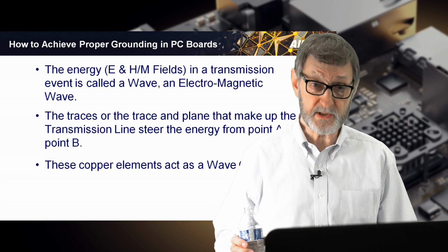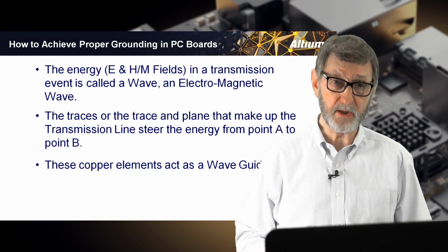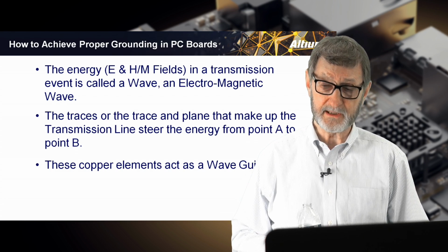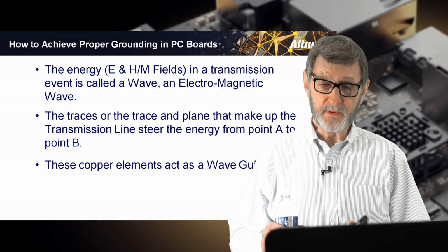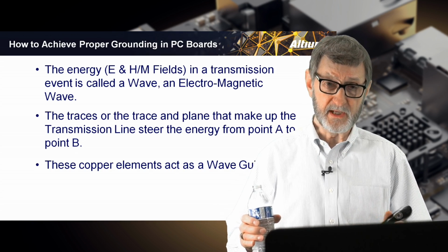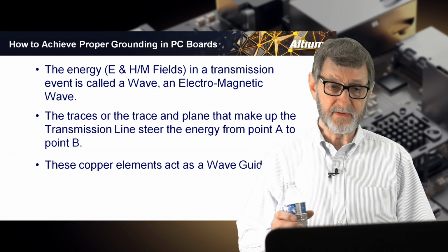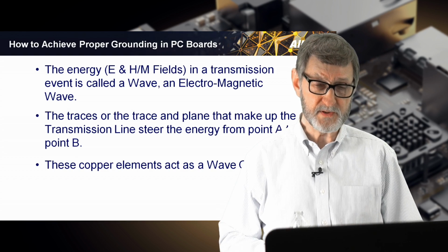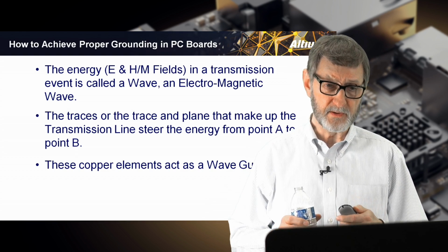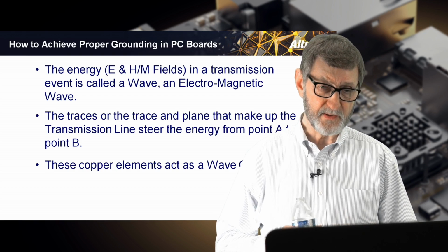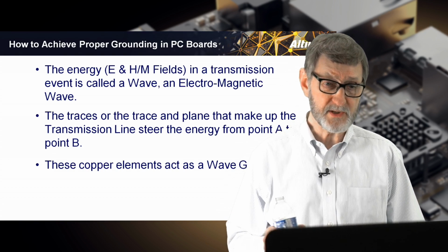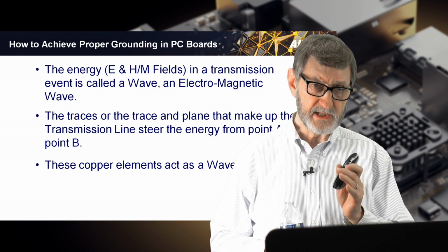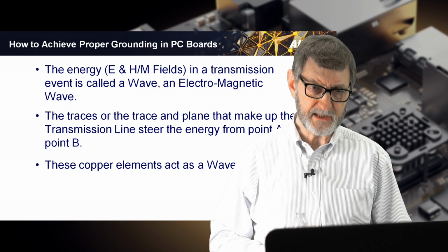Could we just launch the energy into the dielectric? Yes, we could. We do it all the time in air with radio broadcast. That's exactly what radio broadcast is, energy being launched into free space so that it gets picked up by an antenna at the receiving end so people can listen to it, or in the case of television, watch it, or so on. We do it with Wi-Fi, we do it with virtually everything that's a broadcast medium. We could launch the energy into the circuit board dielectric. The advantage of giving it a trace to follow is that it offers a lower impedance path, and that's the concept.